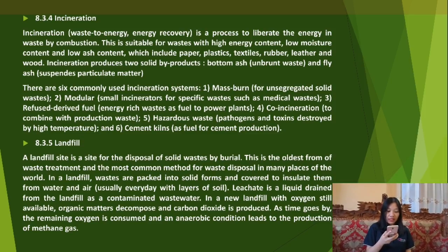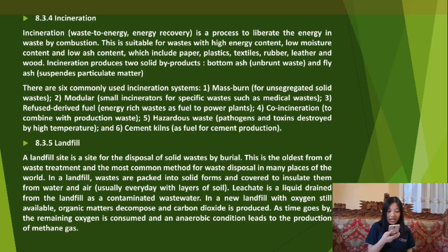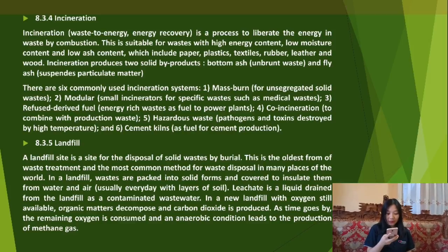834. Incineration. Incineration, waste to energy recovery, is a process to liberate the energy in waste by combustion. This is suitable for waste with high energy content, low moisture content, and low ash content, which include paper, plastic, textile, rubber, leather, and wood.